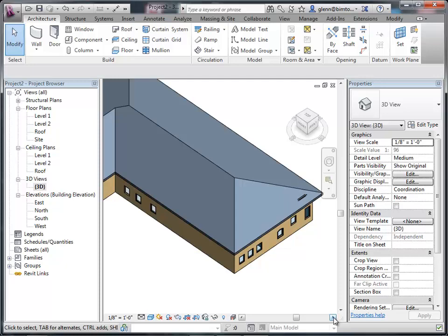An ADA compliant bathroom. Okay. If you aren't sure what an ADA compliant bathroom looks like, a handicap compliant bathroom, check out the bathrooms between here and Coupa, down in that little hallway going straight between here and the coffee place. Those are really good examples of ADA compliant bathrooms. The ADA compliant bathroom is around 5 feet by 8 feet, because what really drives the dimensions is you have to have a 5-foot diameter circle that someone can navigate around in a wheelchair.